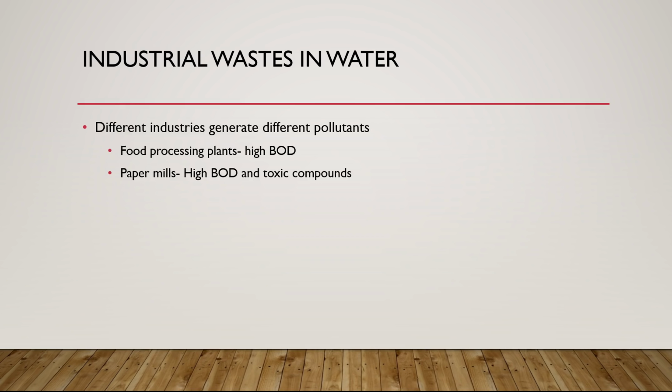All right. Industrial. One of our biggest water polluters is actually the food industry again, so tracing that back sort of to agriculture, but food processing in this case. So the food waste gets put out into waste pools, right? And those greatly increase the biological oxygen demand because those food wastes do have to decompose. Bacteria consume that food waste to decompose it, but use up a lot of the oxygen in the process.